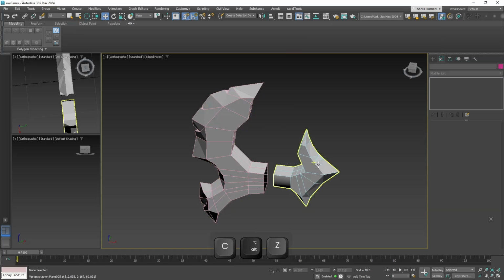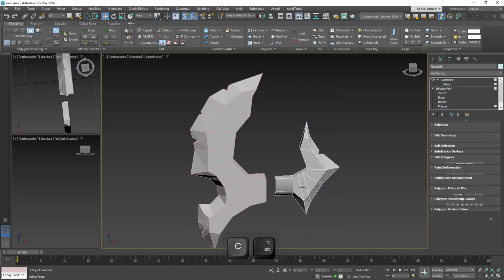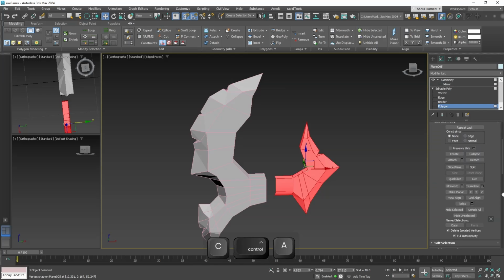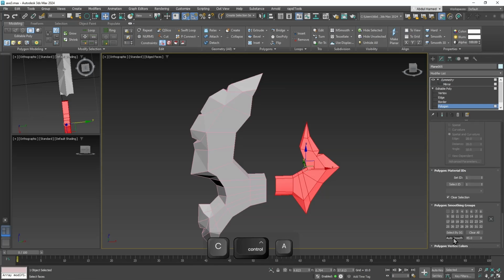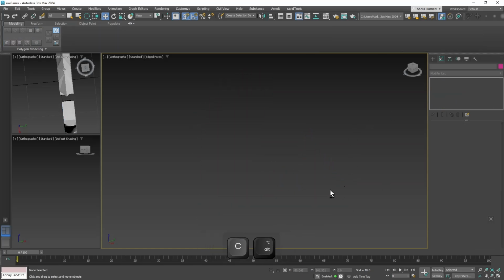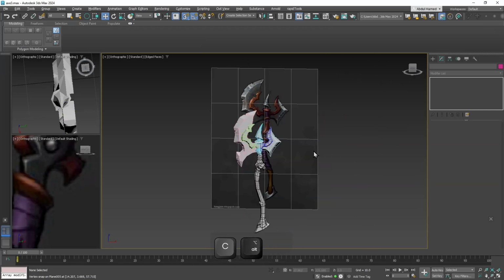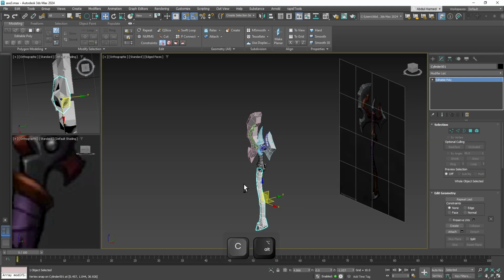So far this is good, but this one right here, it seems to me that the faces need to have their smoothing group recalculated, so I want to change that to 30 degrees and auto smooth. And let's do unhide all. And now we have the entire element.